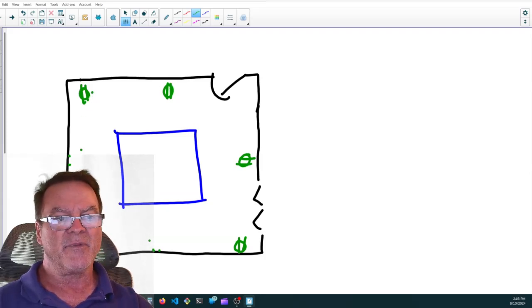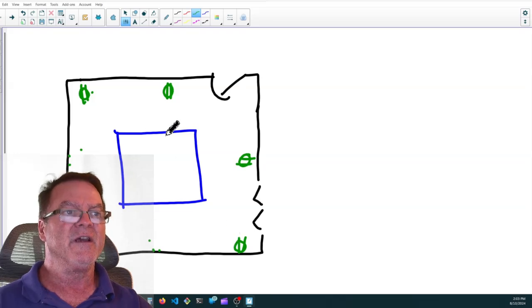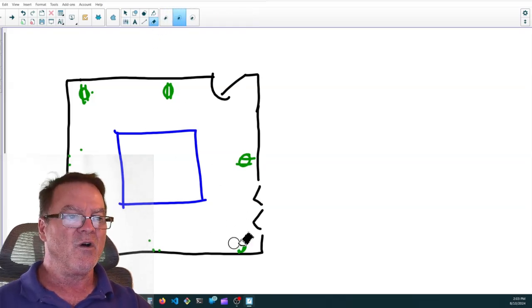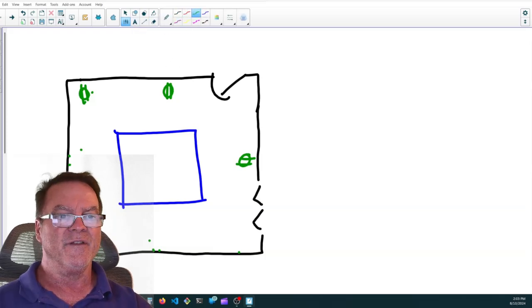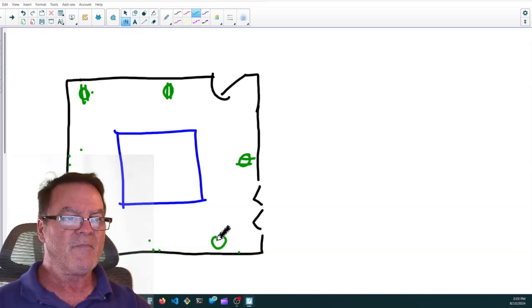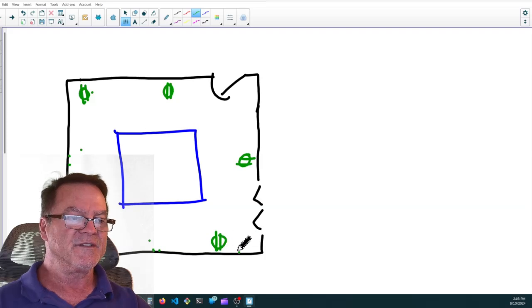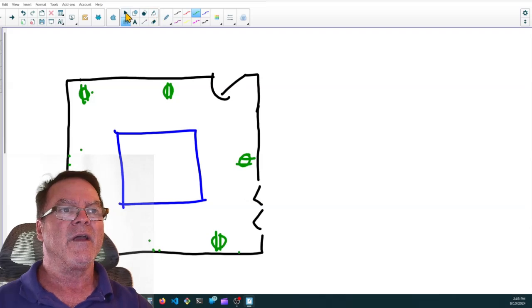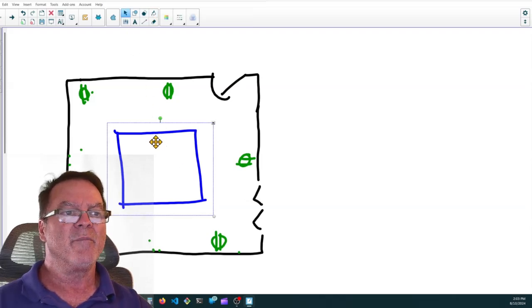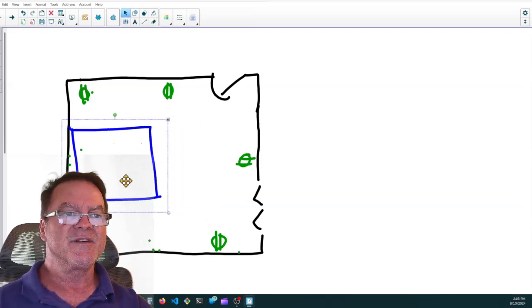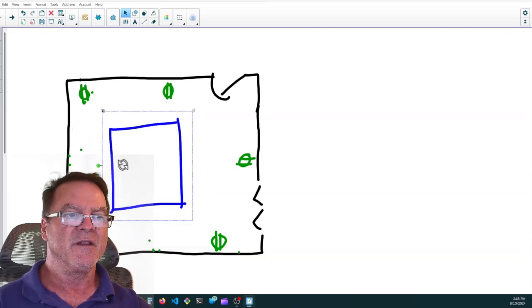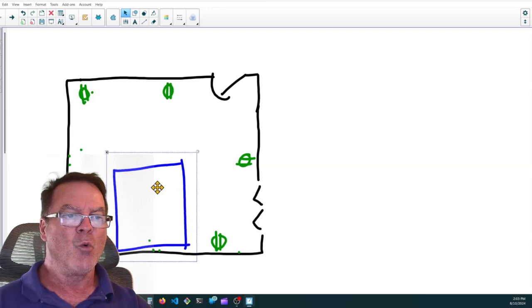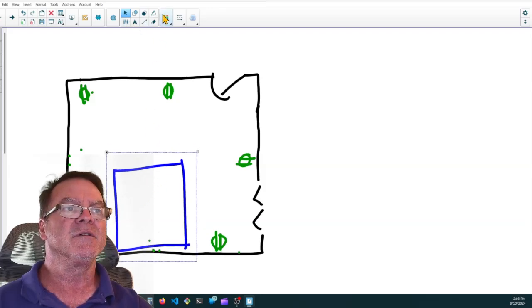And this other one will end up in a corner, and then we'll measure 12 feet, and we'll put the last one over here within 12 feet of this receptacle. And hopefully we're within 6 feet of this wall space here. That way, when we put our bed either up against this wall, or if we want to put it up against this wall, we can put end tables.